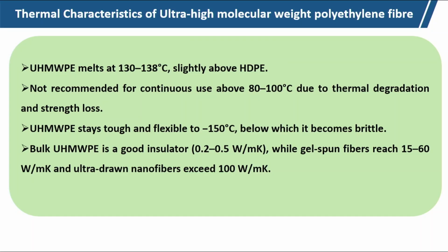Bulk ultra high molecular weight polyethylene is a good insulator, okay. Thermal conductivity is 0.2 to 0.5 watt per meter Kelvin, while gel spun fiber reaches 15 to 60, so the conductivity increases, and ultra drawn nanofibers exceed 100 watt per meter Kelvin.